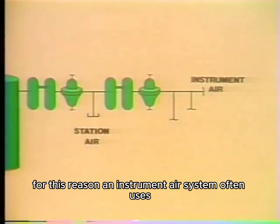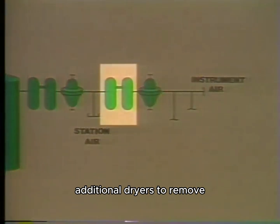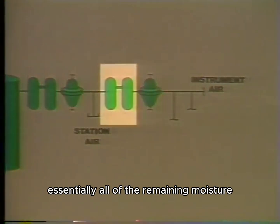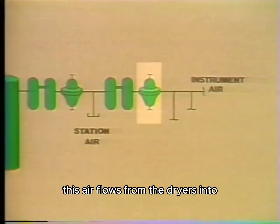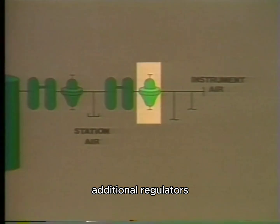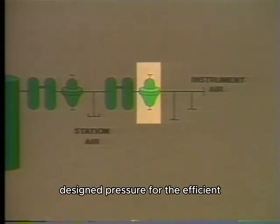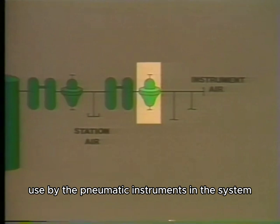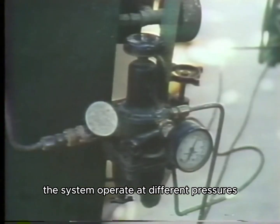For this reason, an instrument air system often uses additional dryers to remove essentially all of the remaining moisture and contaminants in the air. This air flows from the dryers into additional regulators that reduce the air to an acceptable designed pressure for the efficient use by the pneumatic instruments in the system. Many instruments in the system operate at different pressures.